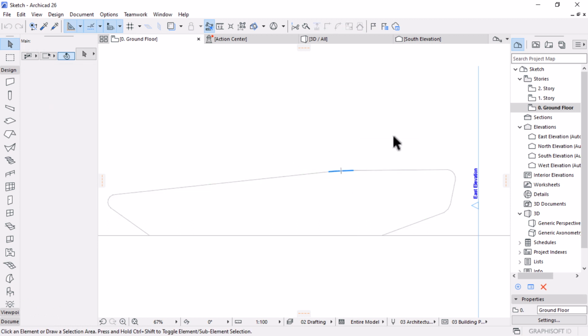There are different ways of approaching this in ArchiCAD. You can use a complex profile, and then use a beam or a wall tool to place this in your ArchiCAD. Or you can use a combination of both profile and the 3D tools like walls and roofs to assemble this, but you have different portions.